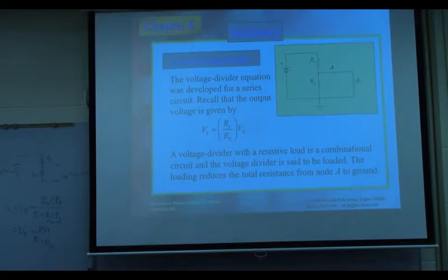Okay, again, let me check if you still remember. If I have 10 identical resistors in parallel, each one is 10K ohm, what is the total resistance? 1K. Everybody agree? Yes, 1K, right? 10K divided by the total number. If these 10 are in series, it will be 100K. Multiply, okay?